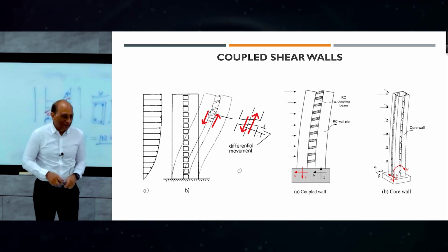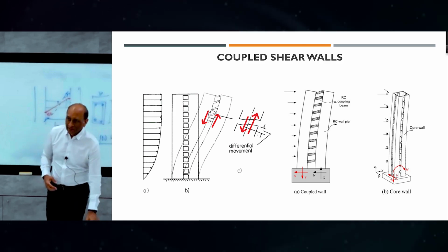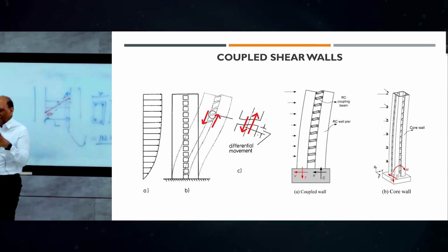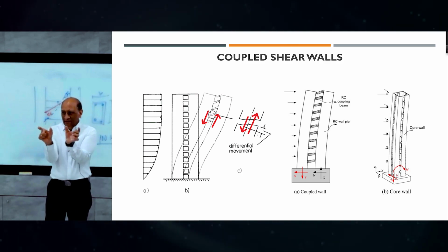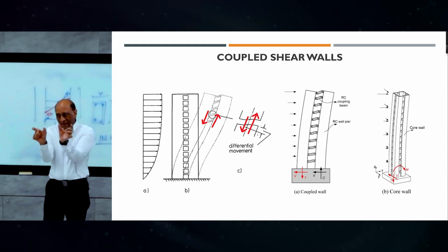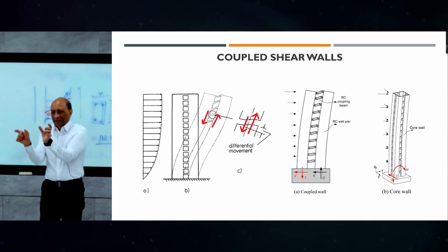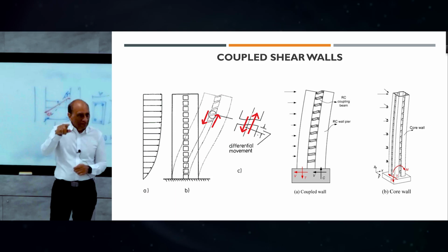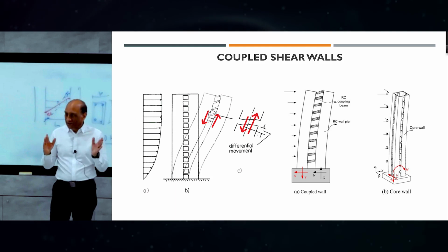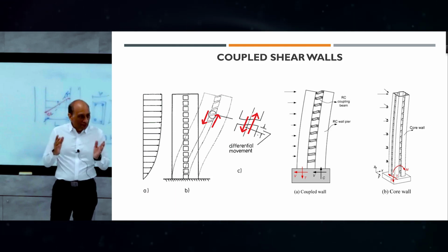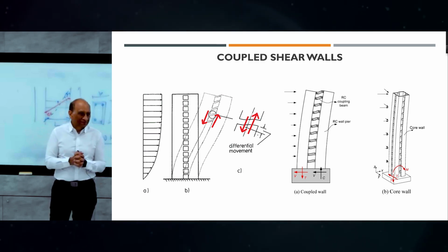So which means we put like a certain fuse in the wall that will make sure that the two shear walls are coupled to a certain level. And beyond that, that coupling will remain, but deformation will increase, but it will not break. And sometimes that extra moment will cause it to crack, yielding will occur, but people can come and replace it. But it will not let the building fall, because if it breaks, everything goes, because the walls will become uncoupled, and we don't want that.